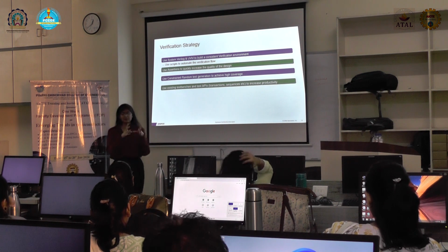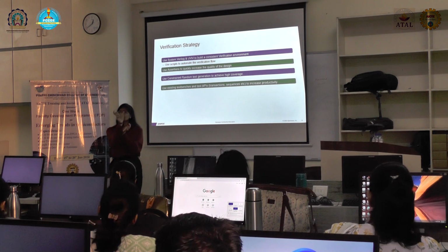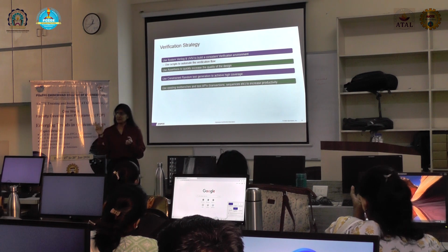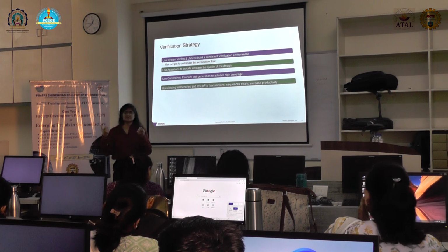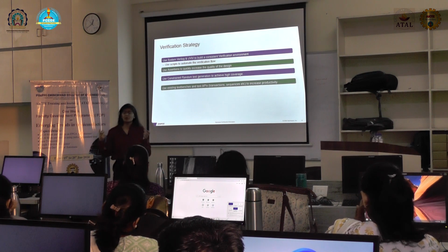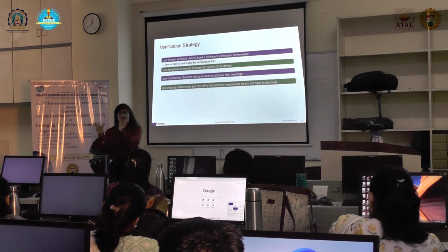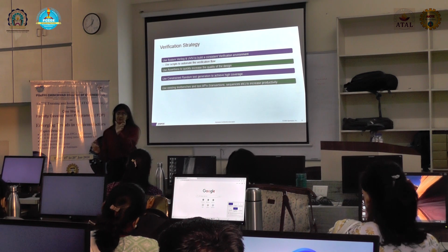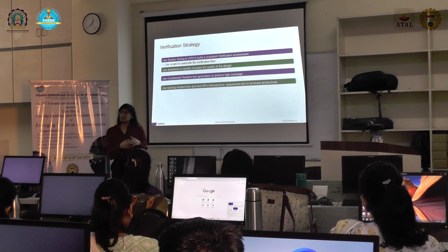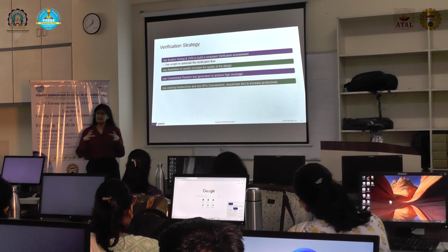And in the test, what we'll do is we create two functions, a write function and a read function, and make those two functions generic, with arguments address and data. So address and data are generic variables. Wherever we want to write or read, we call this function specifically for write at any address, or for data collection at any address. For this sort of functionality, we create generic APIs and use them across the testbench itself.